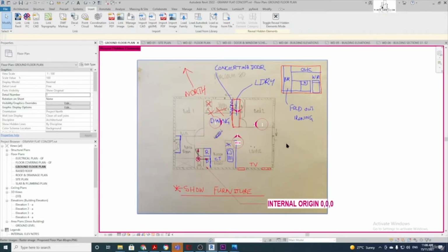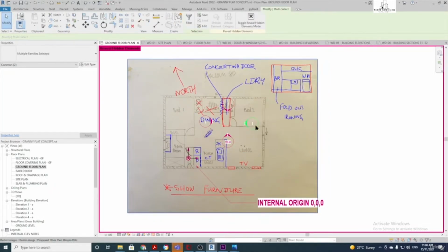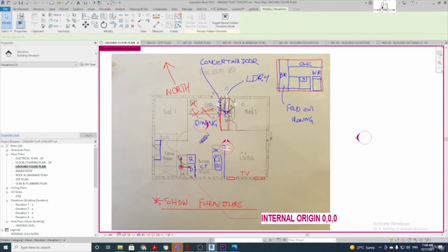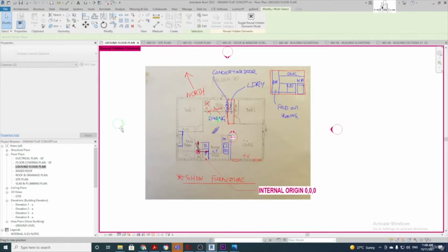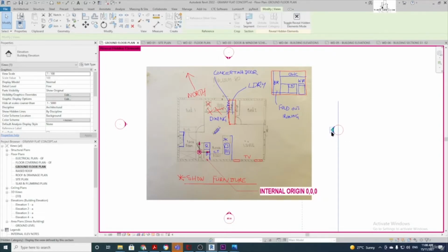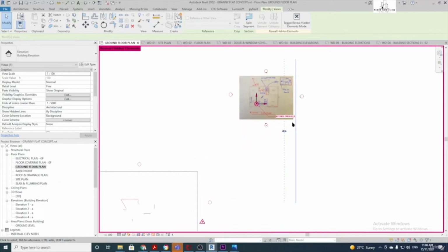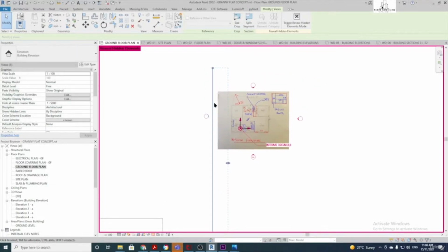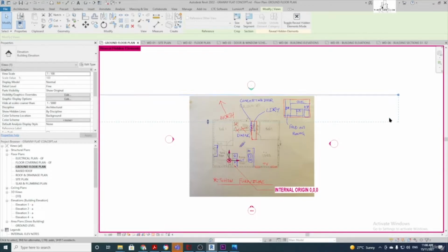Now what we're going to do is individually select our elevation markers. So you want to select the elevation marker as well as the tab, pull it out to the side here, do the same with the other ones, pull them all out to the side. Like that. Now click these little arrows and we can see where our elevation line is. So we'll drag that up to the side of the building, like this. Same as this one, pull it up like that. Next one, pull that up. So the side of the building. We can adjust them a bit further later on, but we'll just get them roughly in position for now.